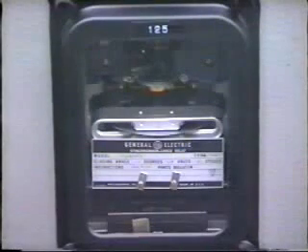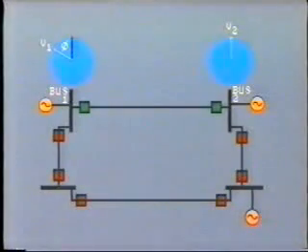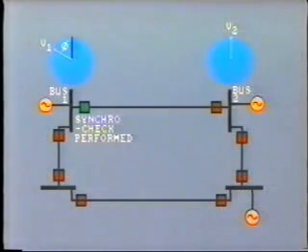If single-pole tripping and reclosure is not installed, then another method is to use a synchro-check relay to measure the phase angle difference. In this arrangement, reclosure takes place first at one end of the line only, while the synchro-check is performed at the other end.